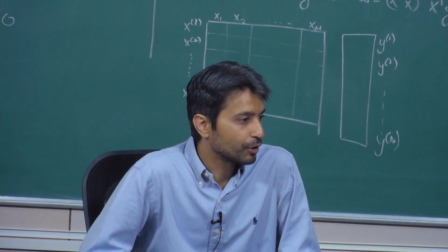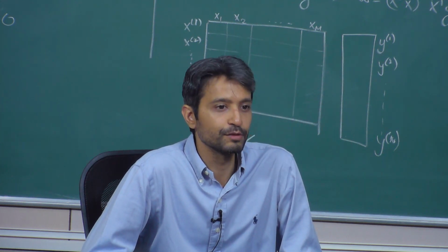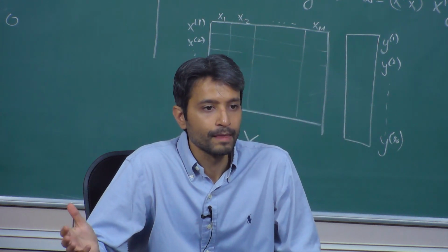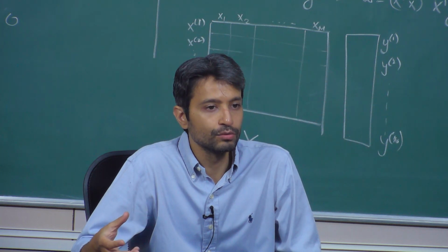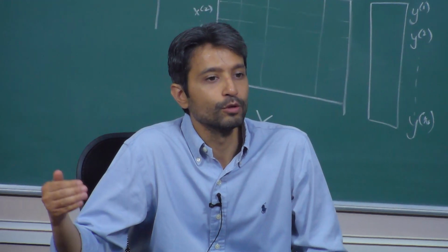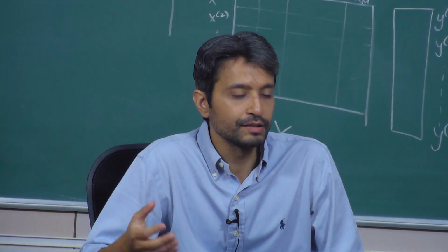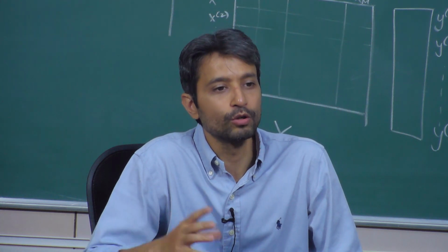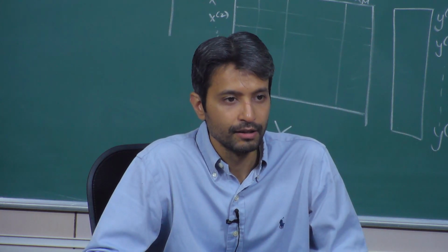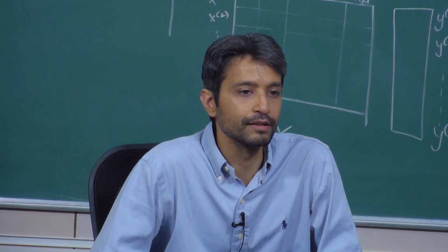Yeah, so what you want is those compositions which have high hardness but a particular element is not present, or a particular element is of low concentration. So see, a machine learning model allows you to make predictions for everything, right? The word that I like to use is candidate set. You have a candidate set for which you want to make predictions. In your case, the candidate set can only be those alloys which have a low concentration of that particular element. Only for those alloys, you go ahead and make the prediction and check whether any of those have a high hardness or not.